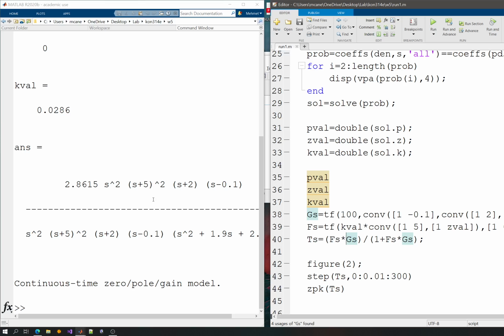So the basic message I'm trying to give here is that designing a pole zero cancellation at the origin is not a good idea. It takes quite some effort to deviate from s plus 1, but exactly at s, it's too close and it's too risky.